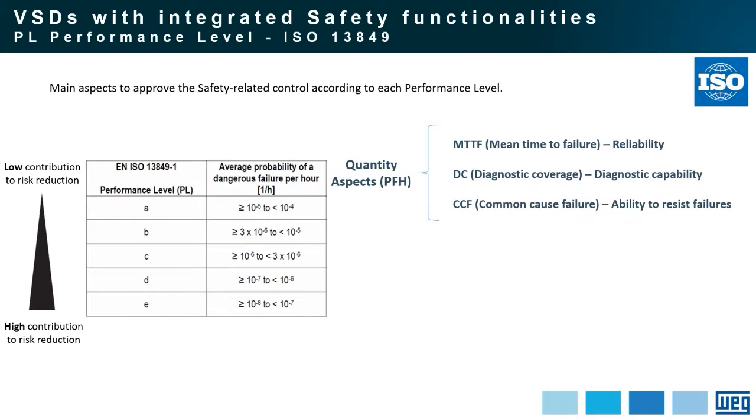Additionally, there is the definition or the statistics concerning diagnostic coverage or diagnostic capability: how the components will monitor and how the components will find internal failures. Another one is the common cause failure statistics that in the end will check the ability to resist failure.